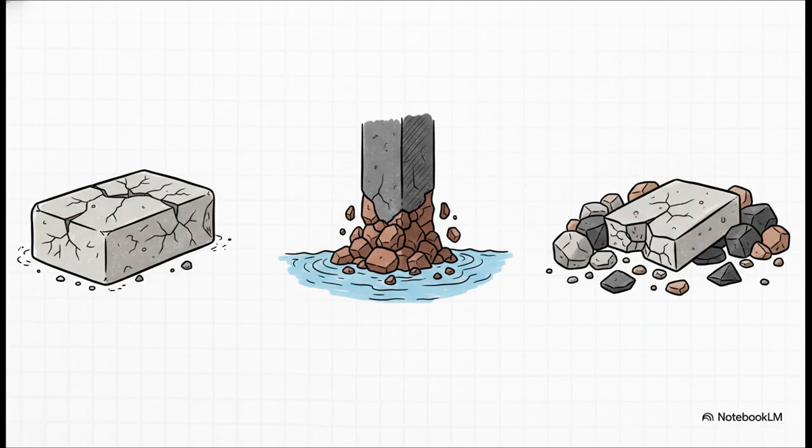Yes, lime provides strength, but too much of it directly causes cement unsoundness. That means it will dangerously expand and crack after setting. Error number 2, choosing a weak, highly porous sedimentary stone for high load-bearing bridge foundations. It will rapidly degrade under hydrostatic pressure.